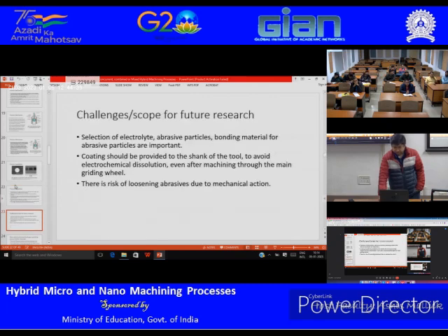I think I already talked about the selection of electrolyte, abrasive particles, and bonding materials. All those are important factors to be considered for future research. Coating should be provided to the shank of the tool to avoid electrochemical dissolution. We talked about that. Then there is a risk of loosening abrasives due to mechanical action, right?